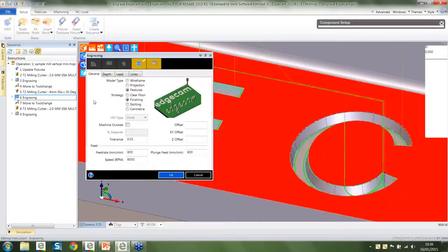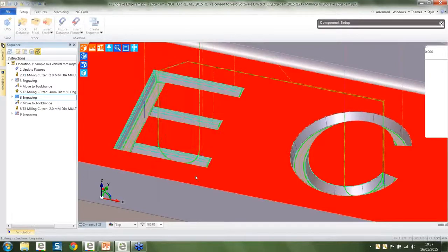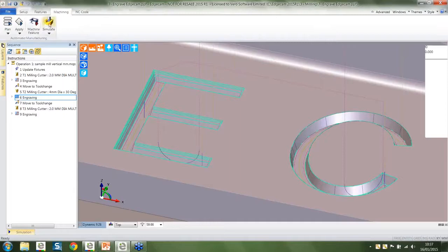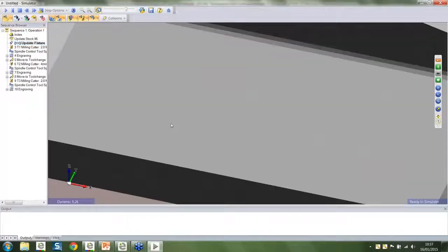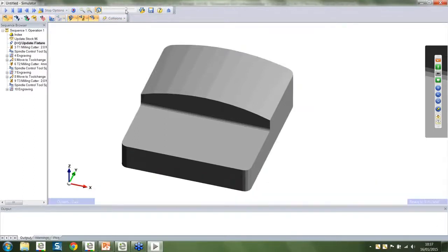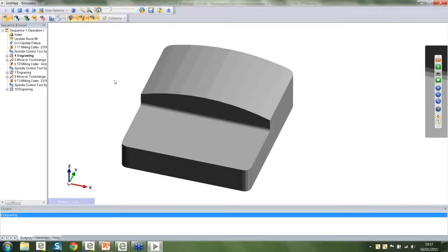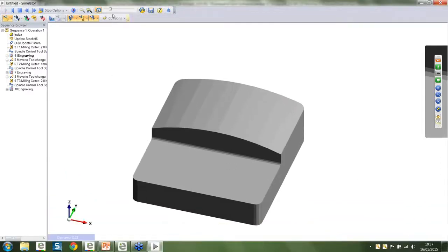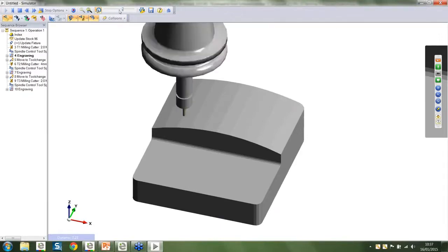The other item that we'll see in engraving is the finish, and this is very, very specialist. We tend to find that engravers will use a taper tool, and when the tool reaches a corner, internal or external, the tool ascends to the top and then descends, feeds down to the base, and it's actually forming the corner for us. Let's take that into the machine simulator. It's probably better seen inside the machine simulator, and for purposes of this I'm just going to turn off the machine itself. The first one is the slotting command. All I've simply done is ask the tool to select a center line.